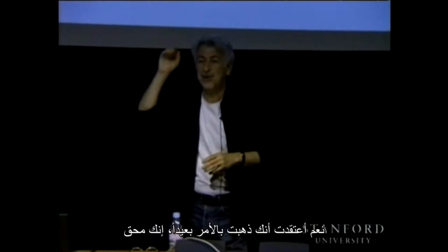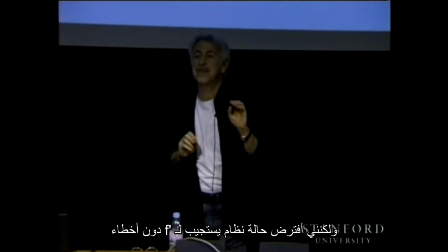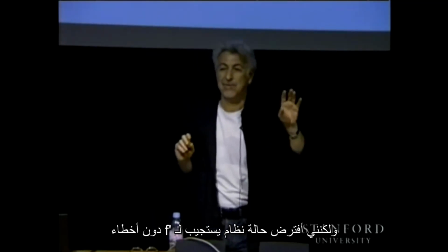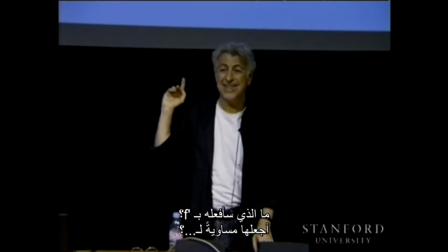Minus the cost of minus x double dot minus xd double dot. Yeah, I think you went too far. That is correct, but I'm just saying if the system was able to respond directly to f prime with no errors, nothing, and my system is x double dot, and I have the desired acceleration x double dot desired, what would I do with f prime? Just make f prime equal to x double dot desired, right?